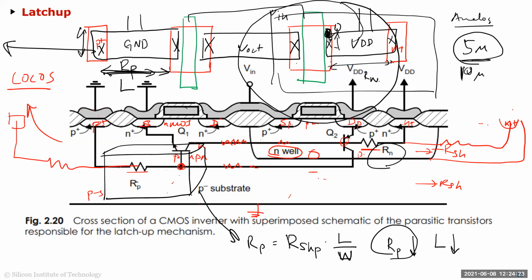So everyone clear about the latch up? So it's basically a parasitic device, NPN, PNP, back-to-back connected. The key to the latch up is, if somebody asks you how to minimize latch up, basically the key is you have to make sure that the substrate and the well contact for all your active devices, your NMOS or PMOSs, wherever you have laid them, should be as close as possible.